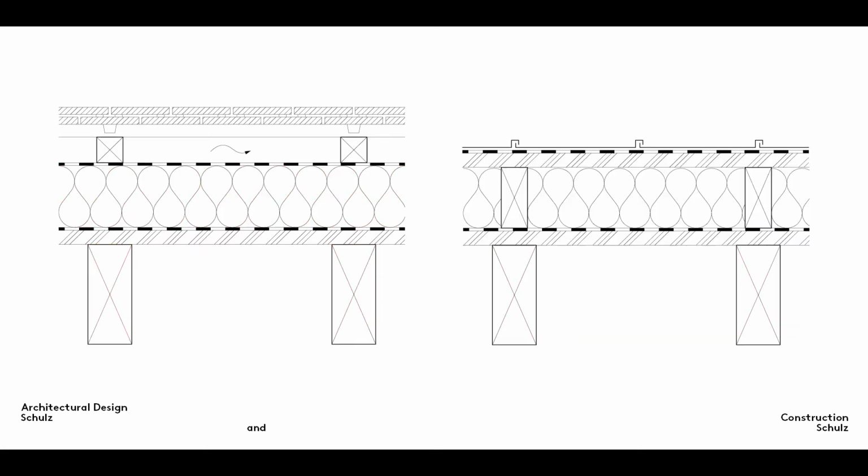If the rafters are to be exposed, however, it will have to be placed above the rafters. The order of the various layers also depends on the type of roof covering, that is to say, the outermost layer to be used. If it is to be covered with roof tiles, a substructure of lengthwise and crosswise roof battens, sometimes referred to as battens and counterbattens, can be used. Tiles also need to be back ventilated, whereas metal roof sheeting requires a flat substructure and is waterproof, so does not need back ventilation. Now let us take a step-by-step look at how the layers are built up on a standard roof with pan tiles in which insulation is laid between the rafters.